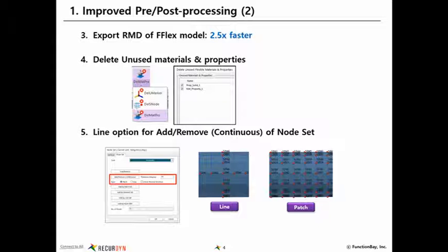And it's a similar feature with these delete unused materials and properties. If you've been adding quite a few new materials and new properties as you've been making edits to your model, you can end up with quite a list. So that's a quick feature where you click once and it deletes anything that's not currently being used. That's a way of simplifying your model visually to make it easier to understand as you're going through it.